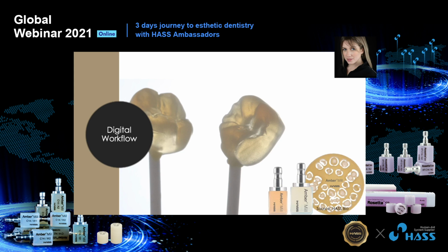For the use in digital technology, the CAD/CAM systems, we can find the ceramic material in the form of a block or a disc of lithium metasilicate. After finalizing the digital process, meaning scanning, designing and milling the case, the restoration undergoes crystallization through heat treatment, and the crystalline structure changes to lithium disilicate.